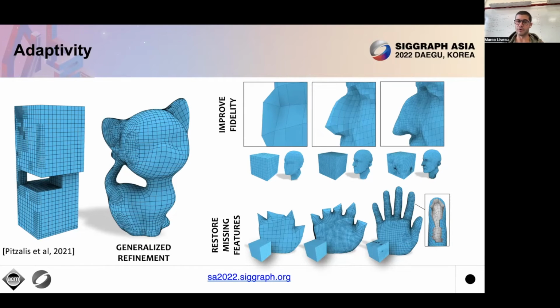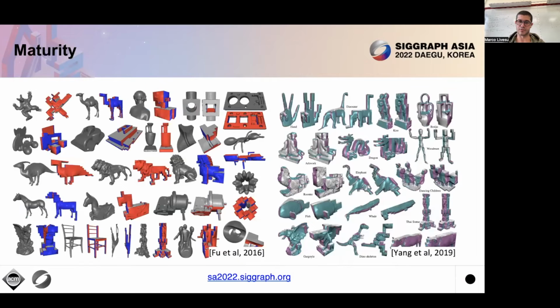Also, if you encode all the tiny features already in the polycube, explicitly, and you apply a regular sampling of that polycube, you're going to have a much bigger mesh, because now the size of the elements depends on the size of the smallest feature. So that could be a good argument to balance adaptivity and polycube generation.